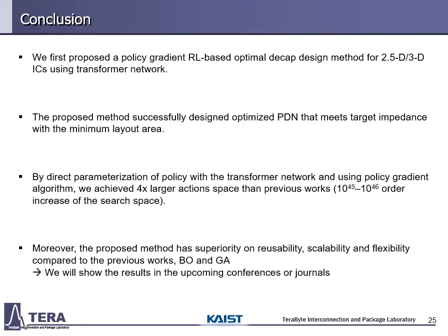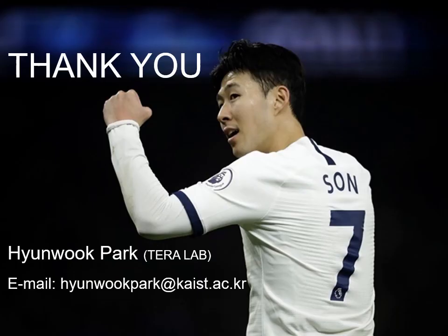Let me conclude the presentation. In this research, we first proposed a policy gradient RL-based optimal decap design method using transformer network. The proposed method successfully designed optimized PDN that meets target impedance with the minimum layout area. By direct parameterization of the policy with the transformer network and using policy gradient algorithm, we achieved 4 times larger action space than previous works. Moreover, the proposed method has superiority on reusability, scalability, and flexibility compared to the previous works based on optimization and genetic algorithm. And we will show the detailed research in the upcoming conferences or journals.